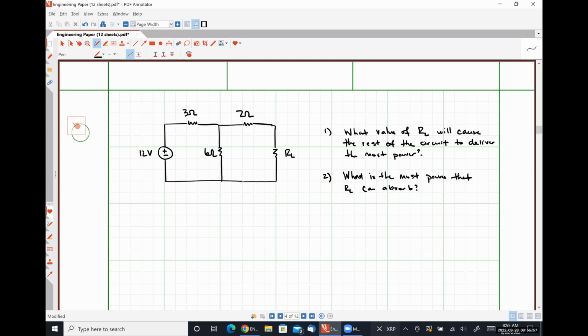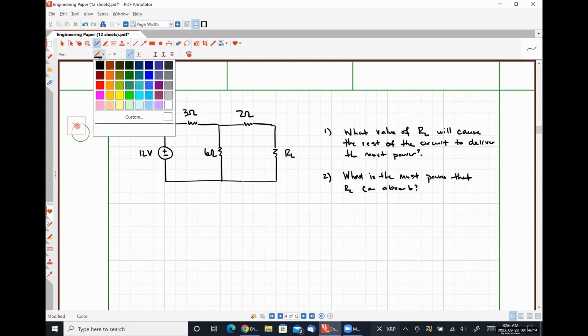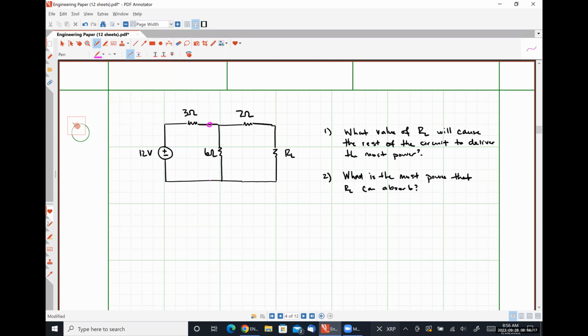So tell me what to do. Let's apply what we've learned today. Okay, so we're going to change the voltage source into a current source. So what Brody is suggesting, and I'm going to go into a little bit more detail than his description, is we disconnect the practical voltage source that I have set aside here with these pink terminals and turn it into a practical current source. Reagan, what should our practical current source be?